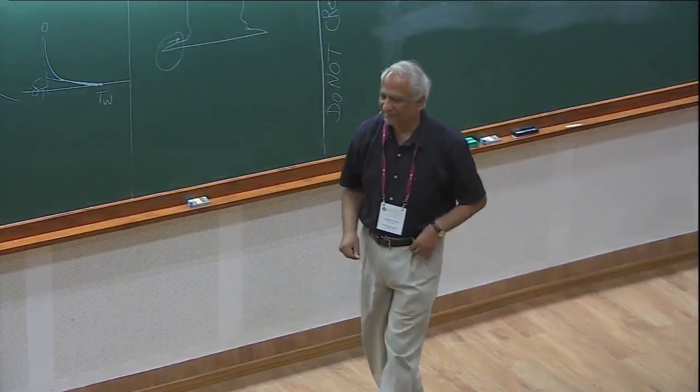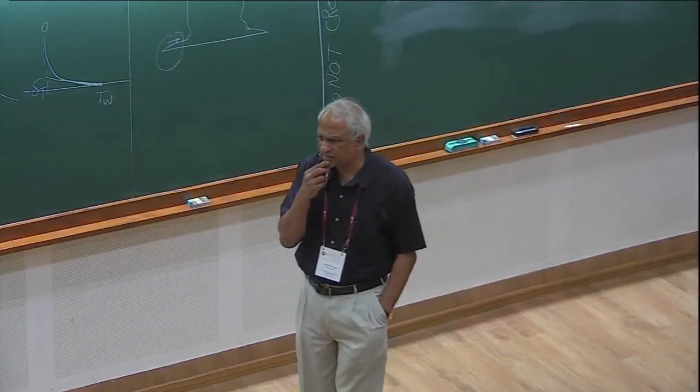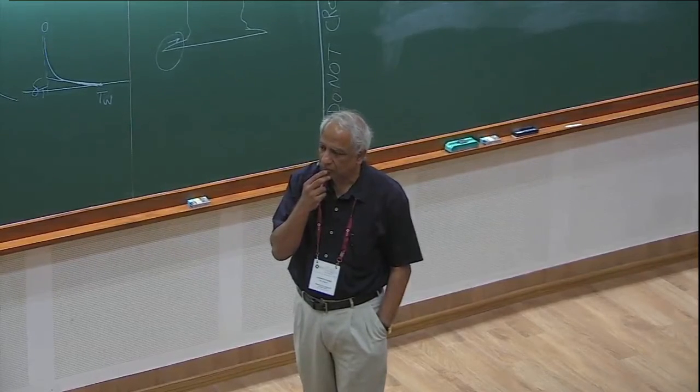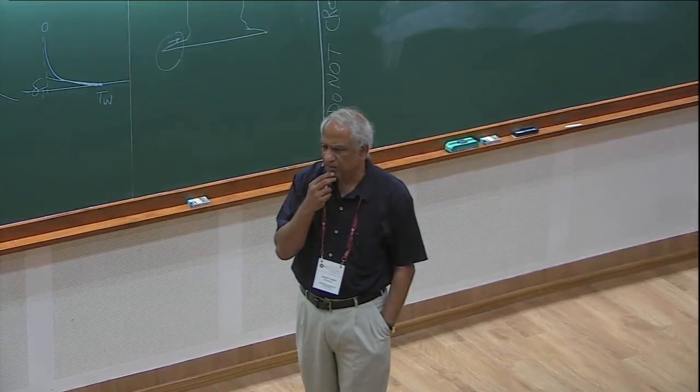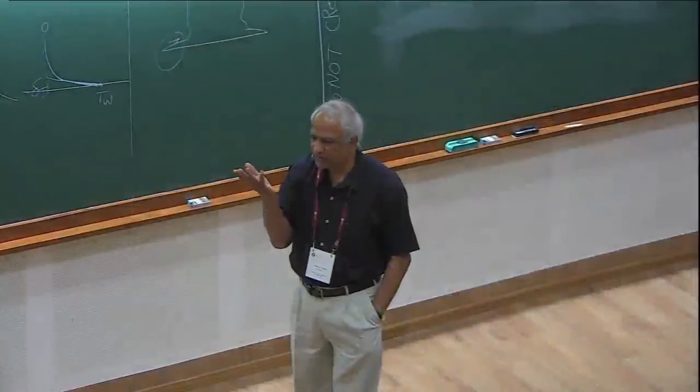So I just want to make another remark that experiments, since I think it's a 2D PIV, unless we get a full 3D picture, it may not be able to give you the predicted value. So that could be the issue. Well, it is a slice of the velocity field. You're talking about the aliasing effect and things like that? So there's a component perpendicular to the velocity field, there's a Uy. Yes, and that should also contribute. When we say a spectrum, it's a combination of all the three components. But all measurements of spectra would be, I mean, with.